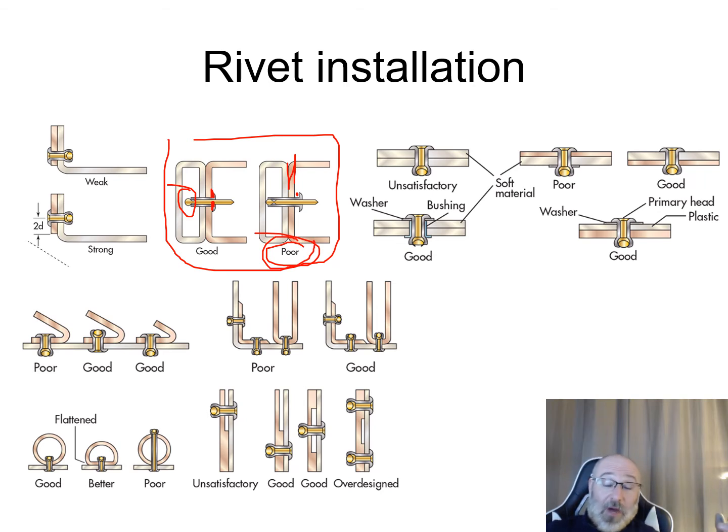Now, another thing to think about, even with the blind rivets, is sometimes it's difficult even to get at one of the areas. So different types of tools, different types of apparatus. Sometimes they have things that have 90 bends on them. So something like this is really difficult to get at. In a situation like this, you can't necessarily come down from the top all the way. If it's cut back like this, sure, then you can. So maybe you need to come from the other side and get that good seal. So which side you come from can be important. And sometimes you don't really have a choice for the situation you're in, where the rivet needs to be located. You can only come at it from one side. So maybe there's a better rivet choice for those types of applications.